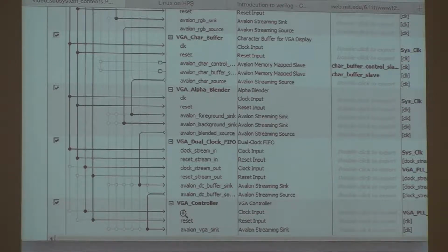So they are using the version 16 university computer, which is fine, but the default VGA is set up for 320 by 240. And you will have to go in and edit pieces of the video subsystem to convert it to 640 by 480. Took me about, I don't know, 3 or 4 hours to figure out how to do that. I think I documented it someplace. I'll try and find that.